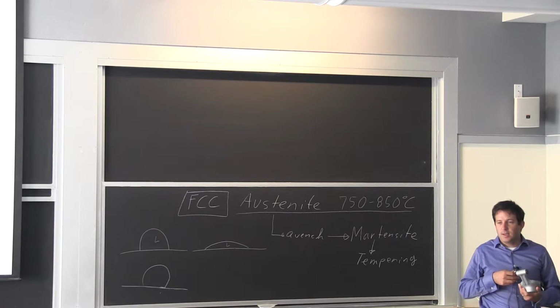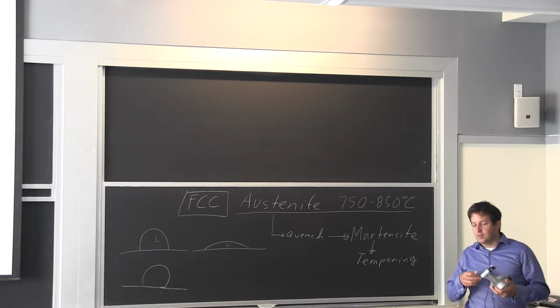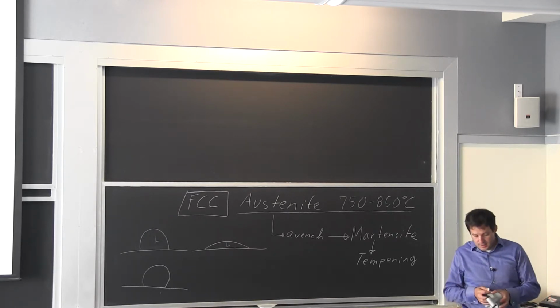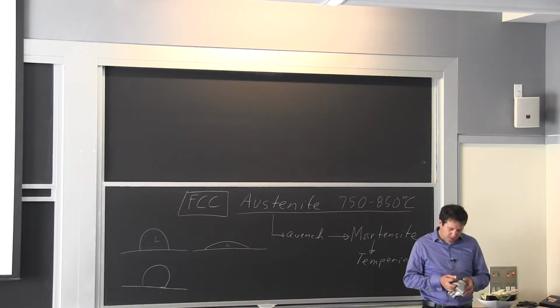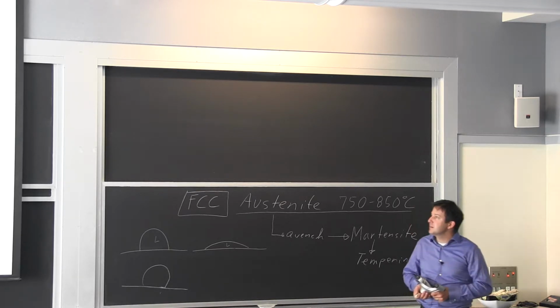It's really easy and cheap to increase the strength, and not so much the ductility. It's some of the ductility. It depends on the alloy, but you really increase the yield strength by adding a little bit of alloying element. And so we're talking about only 4% or so.